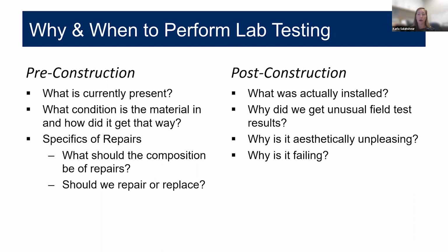Some examples of why we would do testing pre-construction are to evaluate the materials currently present on the structure, the condition or state of the material, assist with repair design, and depending on the extent of distress, realize it may be more advantageous to replace versus repair the material.